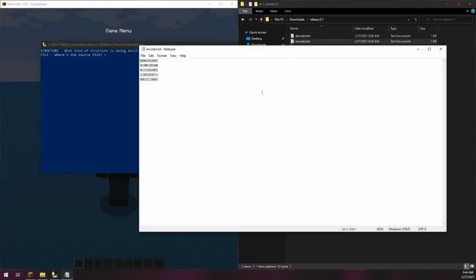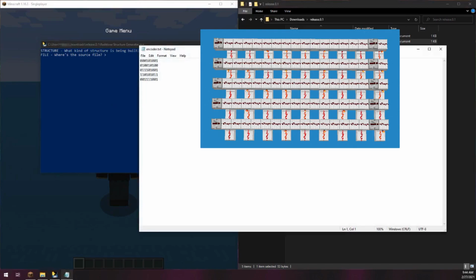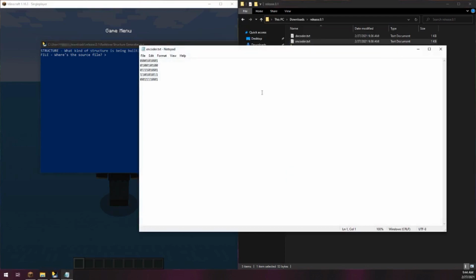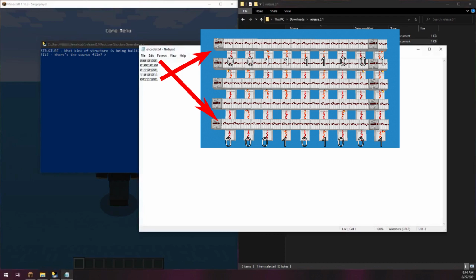And if we open it up, you can see a bunch of ones and zeros arranged in a grid. We can see it's 5 lines, and each line is 9 bits long. So this is going to produce an encoder with 5 active low inputs and 9 active high outputs. You can think of it like each line being a line in an encoder, and when that line is active, that number on that encoder line is going to be presented at the output. The outputs are going to appear as they appear in the text from left to right.